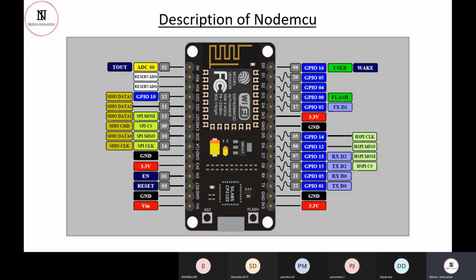Even static electricity on your hand can destroy that chip in a fraction of a second. So we do not want you to waste your money on that. The next issue with that Wi-Fi module is that before using it, we need to put in some AT commands and configure the board first, which works for some boards and not for others. And with this problem of remote connections, we might not be able to resolve that issue either.